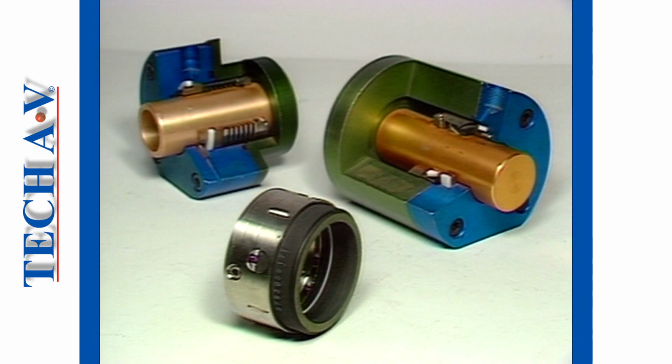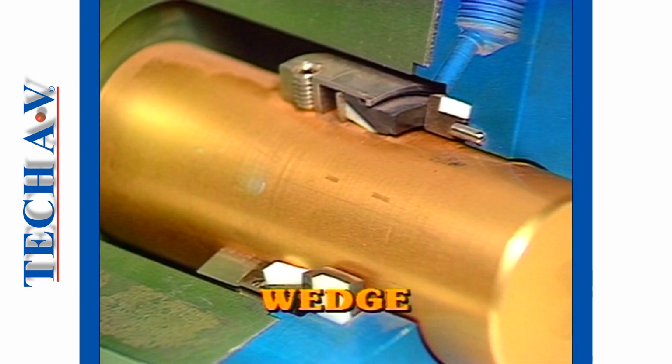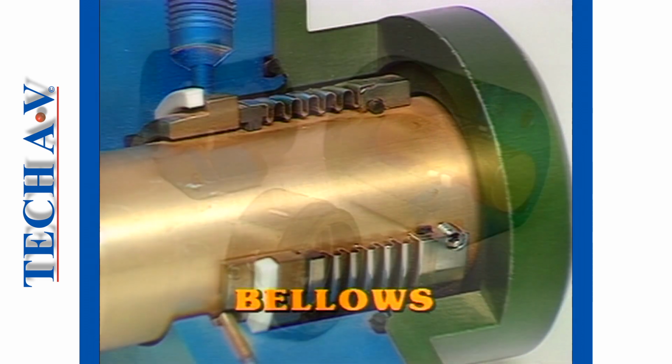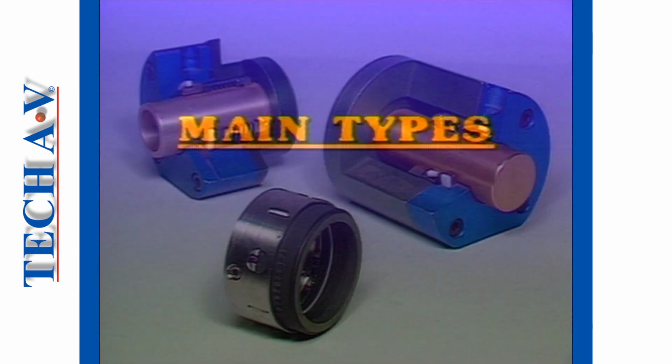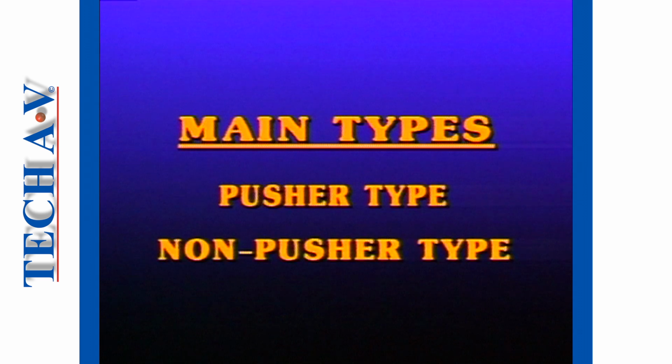Three seal types are commonly encountered, namely O-ring seals, wedge seals, and bellows seals. It is common practice to describe a mechanical seal by its secondary sealing device. There are two main seal classifications, namely pusher type, that is where the secondary seal is activated by spring or hydraulic pressure, and non-pusher type, where the secondary seal is fixed to the shaft.